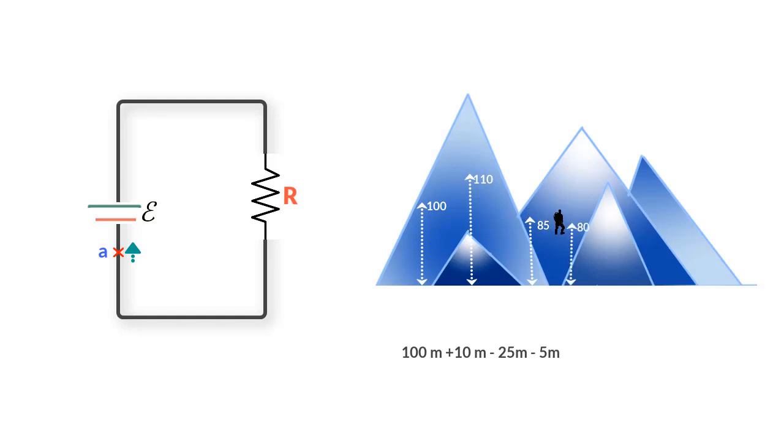Then you finally decide to go back to your starting point and therefore move up 20 meters, so we add 20 meters. Then if we add up this rise and fall to your original elevation, what you'll find is that the final elevation is the same as the starting point elevation, and so this equals 100 meters, which should be the case.